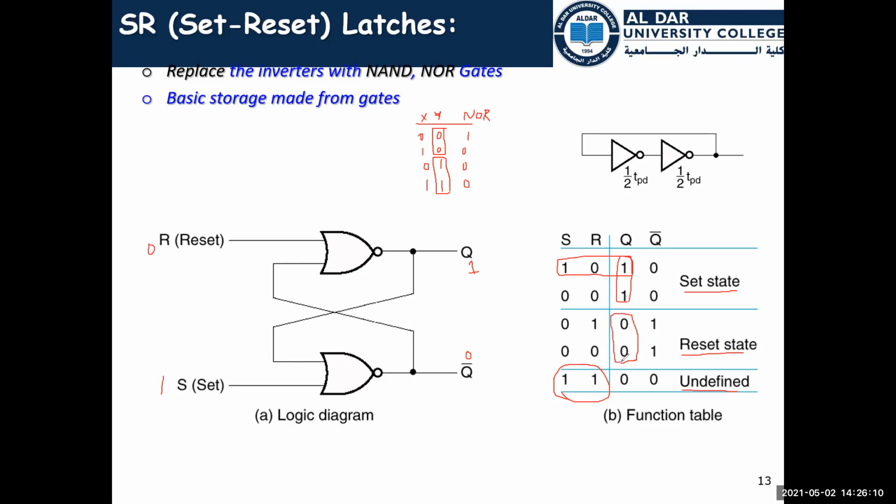If I input 1 and 1 here, we will not be able to get a specific output, because we can say it will be high resistance or a high amplitude value. It is not logic, so we should avoid entering 1 and 1. We will have a solution for this problem by attaching the two inputs together.